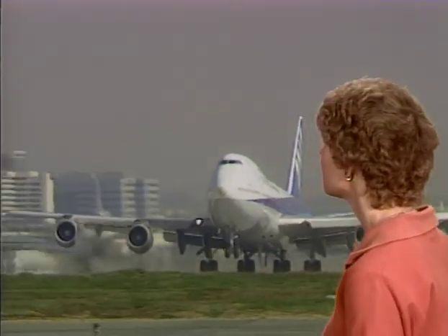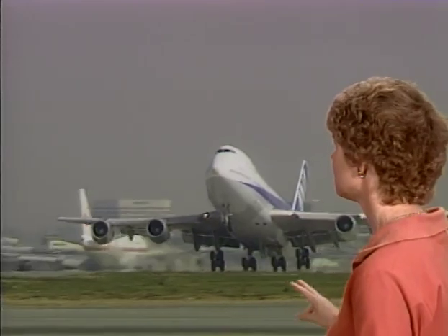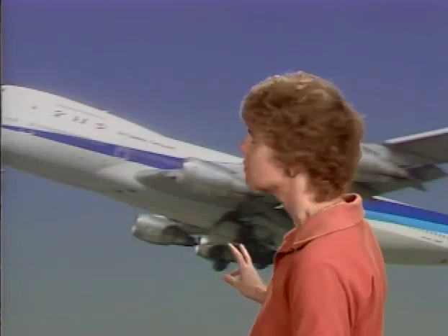Now, let's assume that you've got high-speed aircraft tires. High-speed aircraft tires are very expensive tires. Can they be recapped? Yes, they can. If they've got a sound cord body and bead, they can be recapped, and the number of times they can be recapped depends on what condition the tire is in. So as far as the test is concerned, they can be recapped an indefinite number of times. An indefinite number because it just depends on how good the condition of the tire is, as long as it's got a sound cord body and bead.